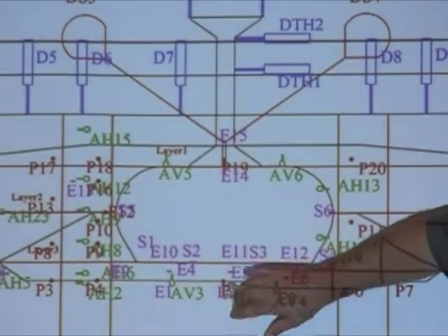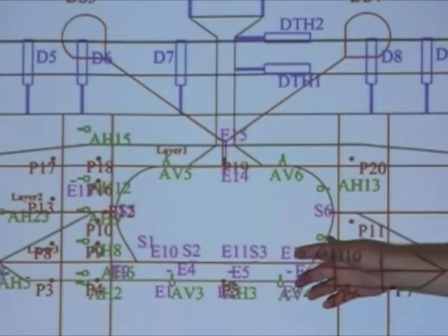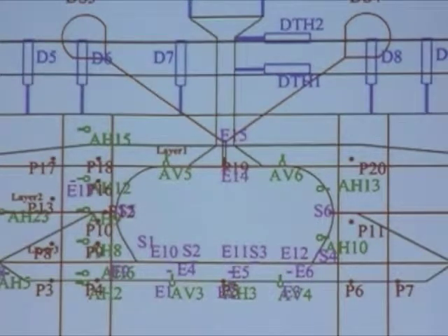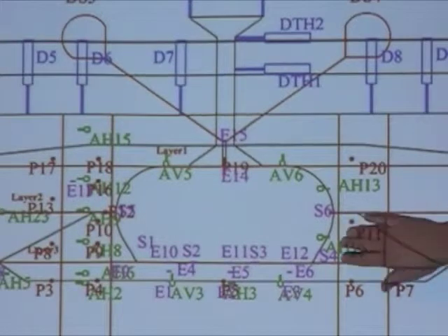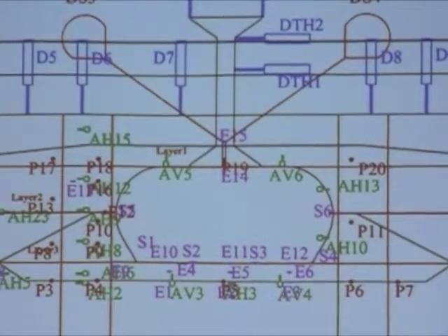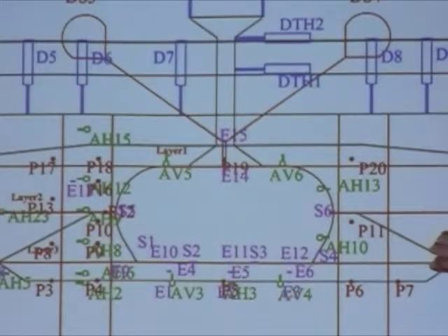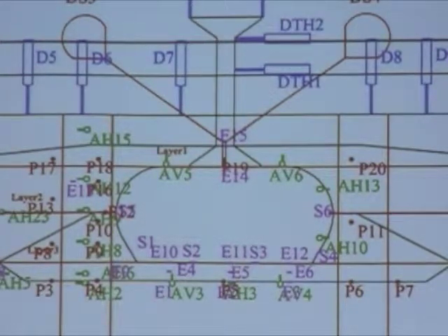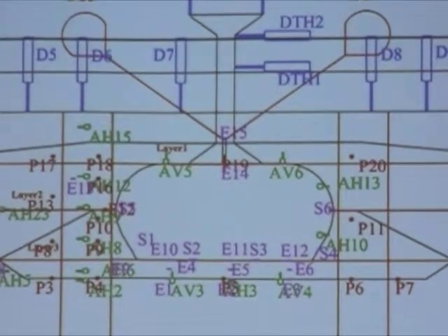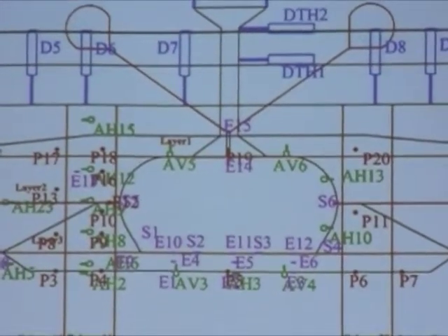We developed these electrode sensors. We actually measure the conductivity of the soil, with electrical properties. We can measure the separation of these two electrical plates, and then as they move, we could actually measure the movement of the tube relative to the bottom of the clay layer with that. So these are new sensors that we developed specifically for this project, because we needed to be able to measure relative movement of this relative to the soil, and trying to measure relative displacement of buried structures is not an easy thing. So a lot of instrumentation, and this was all developed based on the mechanisms that they're trying to study.